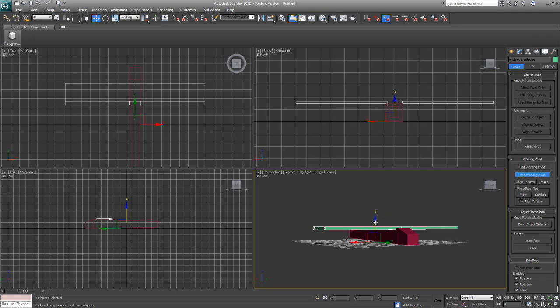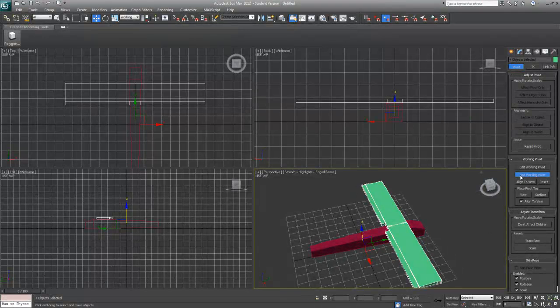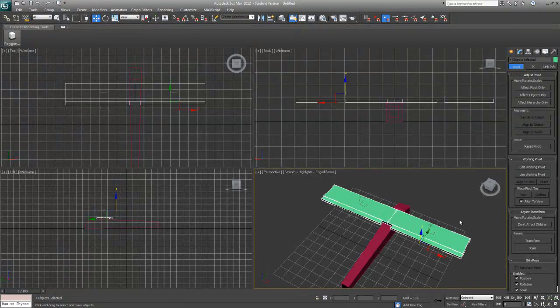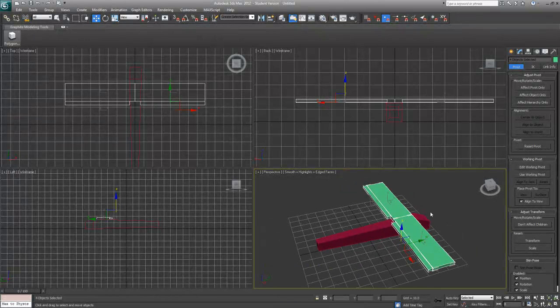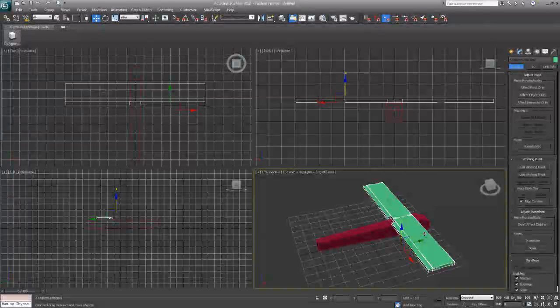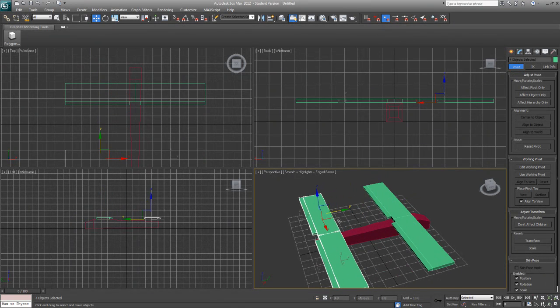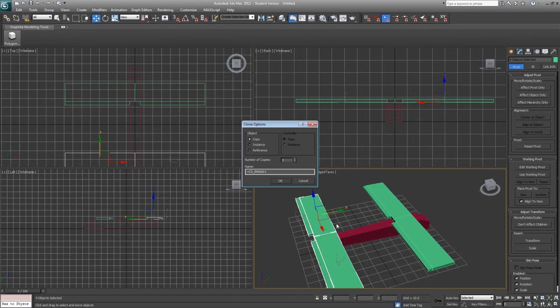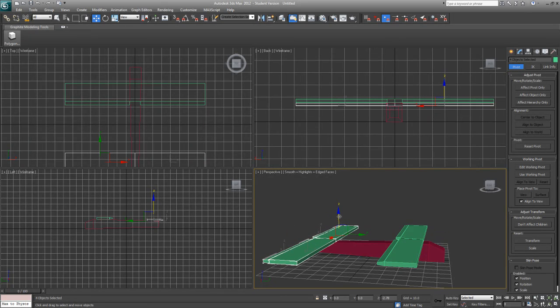Let's lift this up a little bit more, get it right flush. That's good. Turn that working pivot off that we used for the mirror copy. Alright, so now we've got everything selected. Why don't we just turn all of this stuff into the horizontal stabilizer. So we'll hold shift, grab the Y, we'll drag this back. We're just going to select OK. We have too many parts to use that box to rename. So now we're going to move this down.